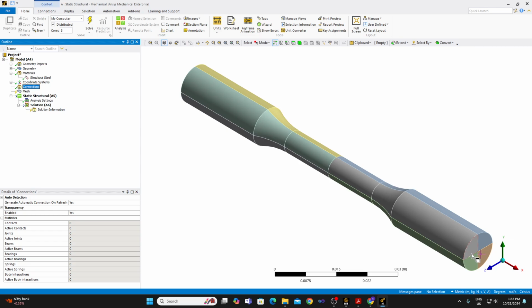One more thing, because there are no duplicate planes, you don't have the option to generate a contact either, because in order to generate a contact, you need a contact surface and a target surface. And if you watch enough YouTube tutorials, you'd realize what I'm talking about.